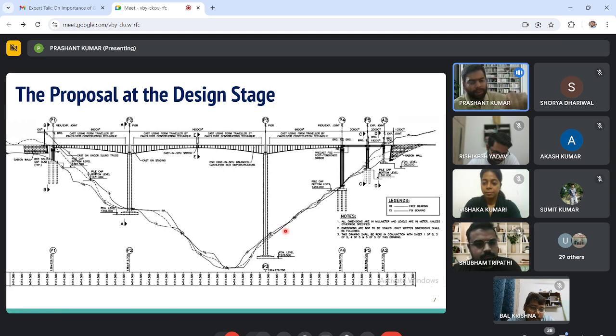So I went to that river on Google Earth upstream, and there was an NH bridge 1 kilometer upstream, and its span was 160 meters, and ours was being constructed downstream. So we had to be much greater than that figure. So finally, we decided on 220 meters. We did the analysis. That was the time everyone understood how important this software is. From that point of time, whatever problem I have, whether geology, hydrology, structural problems, or locating the foundation, it can solve a lot of things, save a lot of time and money, and finally deliver a very quality product.